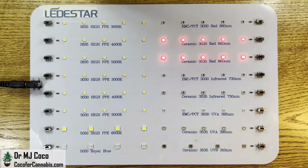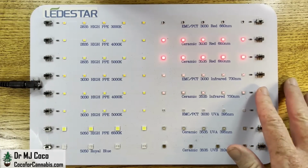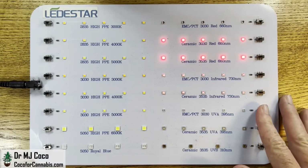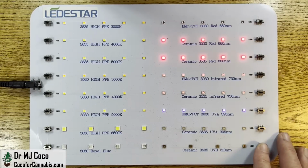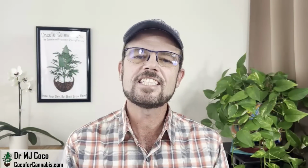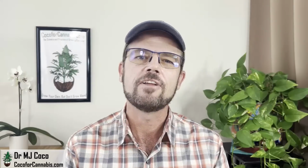Some grow lights will also have infrared diodes at 730 nanometers. These appear dimmer because 730 nanometer light is just at the edge of what we're able to see. And grow lights might have UVA diodes around 395 nanometers. UVB diodes at 310 nanometers are less common. I don't recommend them. I'll explain why I'm not a fan of using UV in grow lights, and I'll discuss the spectrum that we do want for horticulture, and how UV and IR fit into that.